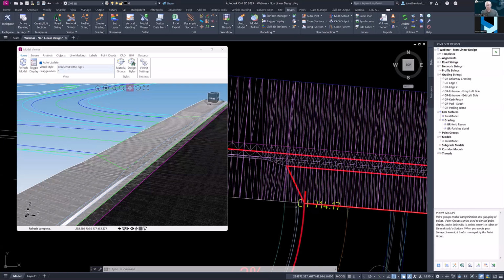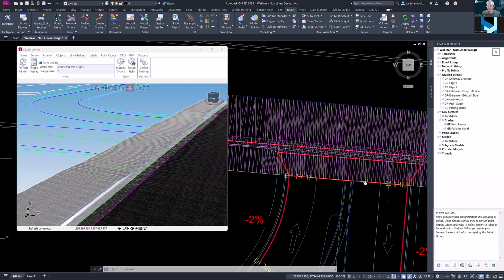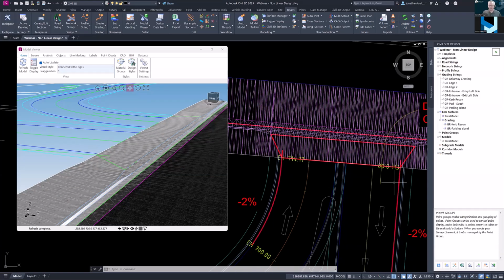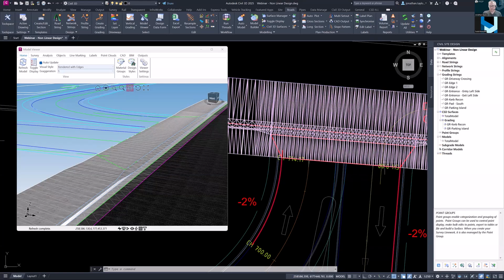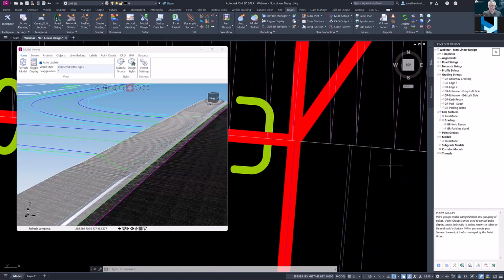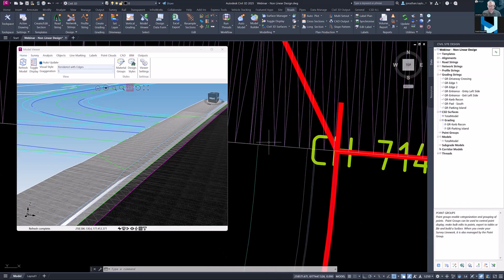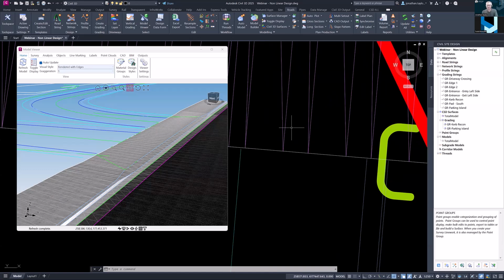All right. Now, the thing about this is that if I'm going to be tying in any design whatsoever, and that design happens to be this road here, and that terminates exactly on the boundary, look at the problems that can happen with trying to tie onto this grading string surface. This is fine. Notice how the edge of my design here just overlaps a small fraction onto that grading string surface. However, because this is not perpendicular, look at what happens on the other side.